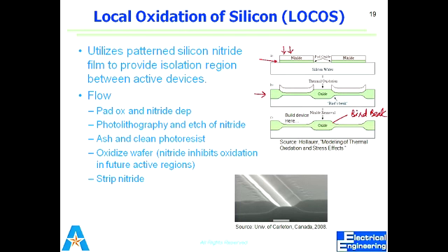In this case, you can see that first of all I patterned my oxide layer, and after that I put the nitride layer as a passivation layer, or as a hard mask. After that, I thermally grow the oxide. When I thermally grow the oxide, it goes under the silicon nitride layer as well. If the height of that oxide is too much, it's because the growth is always two-dimensional.